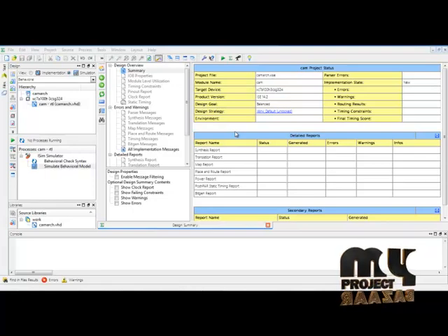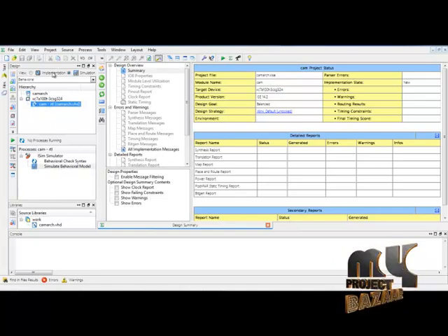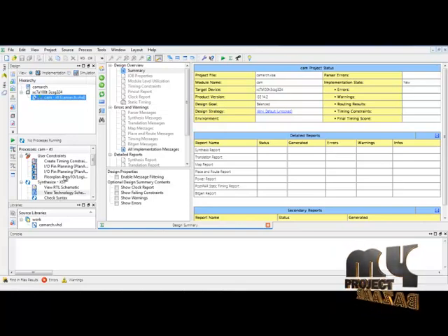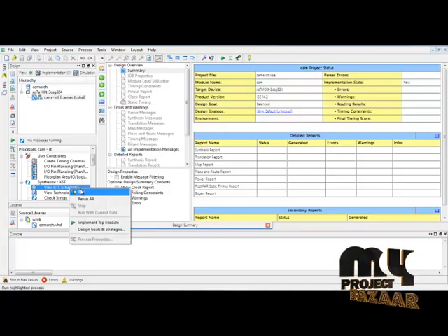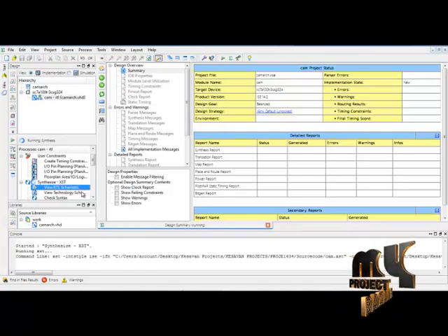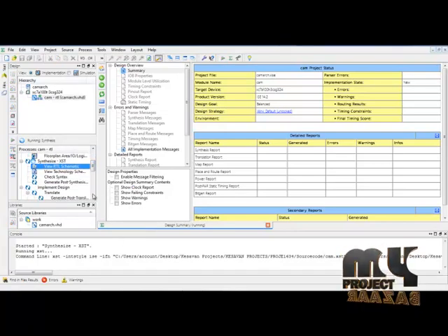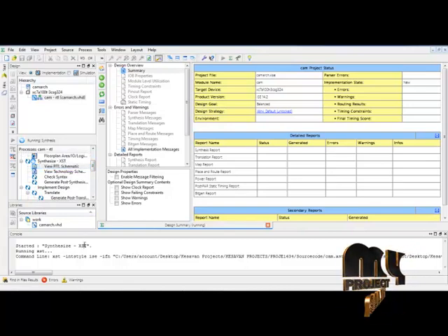Now I am going to explain the running procedure of our project. First, open the cam.vhd file. After that, I first use the RTL schematic diagram by selecting the implementation radio button and then View RTL Schematic, right-clicking it and clicking the run option. This will first check the errors and warnings in the console window.